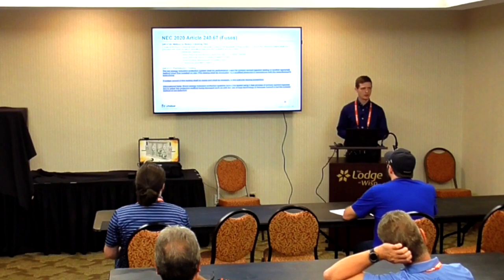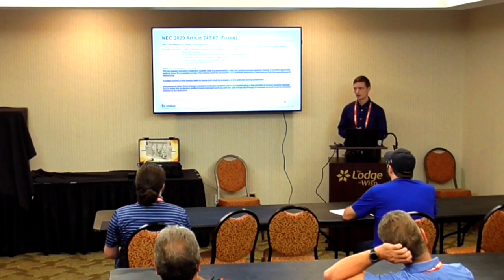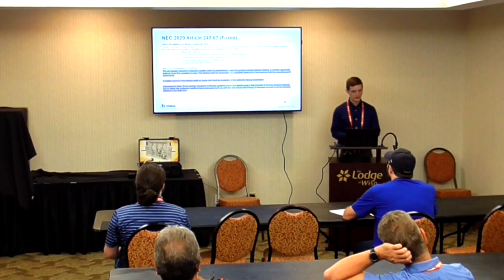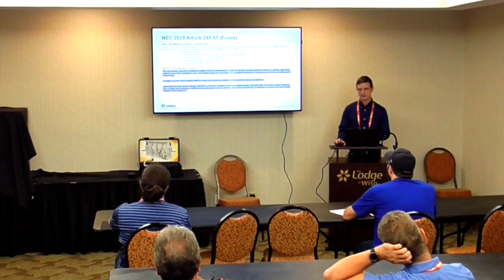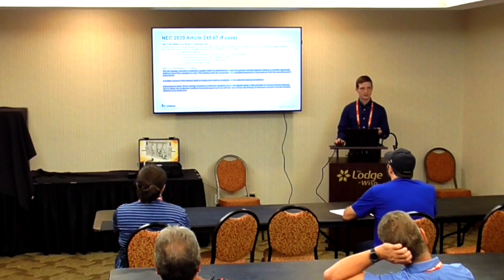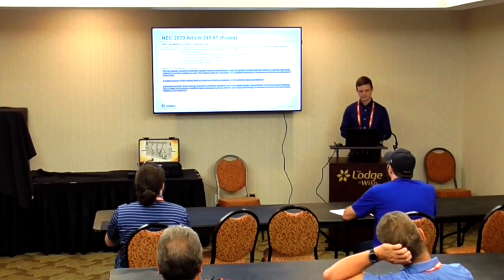That again is something that you can usually find from the manufacturer. Like we at Littelfuse have clearing curves and clearing I squared T available for most of our fuses. So if you can just identify the fuse, they can open properly for your application. Saves you a lot of trouble. Trick to that is, I'm not going to touch on that too much. The operating speed of the fuse is dependent on the amount of current that you have available. So the more current, the faster the fuse is going to operate.